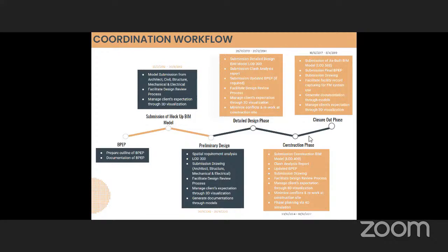And then for the construction phase, the submission of construction BIM, which is LOD 400, will be done. And then also for the clash analysis report and the BEP also will be updated. And then also the submission of the drawing. And then for the closure out phase, the submission of as-built BIM model, which is LOD 500, will be submitted. And then also the submission of final BEP, submission of drawing, and then the facility record capturing for FM system use, and to generate the documentation through models.